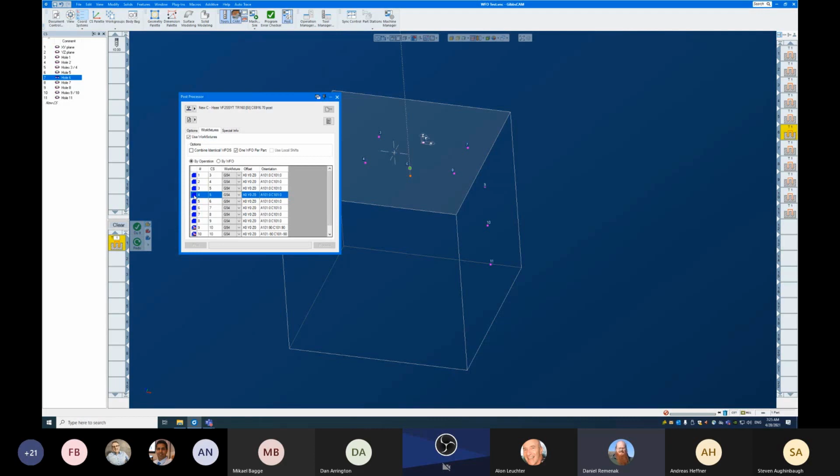For example, if you're doing face milling, you may not care that your X and Y positions are not exactly right for each part. You'll just cut some air on each one, and that'll account for the variation, which means you can go through and set each of your face milling operations to share a work fixture offset, while the more important operations are all getting their own work fixture offsets, and your parts will all come out right.